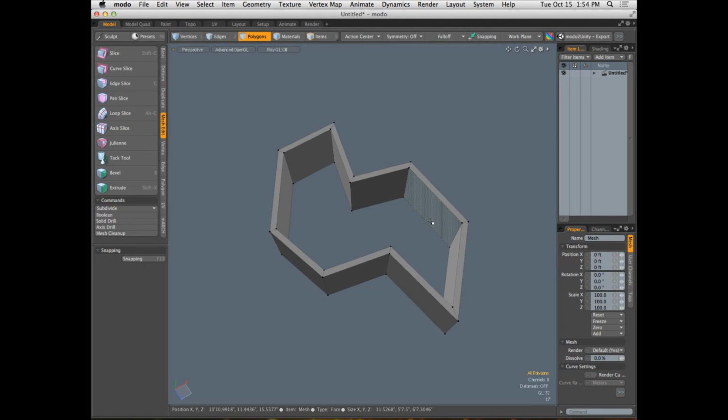So we need to work with a little bit more accuracy. The default values of the pen tool are going to allow us to create shapes like this, kind of custom crazy shapes, okay? But what if I wanted to have 2 walls that were perfectly 90 degrees perpendicular to each other, okay? Well, in order to get access into that world, we have to enable our snapping tools.